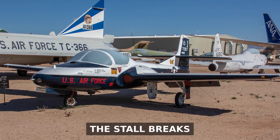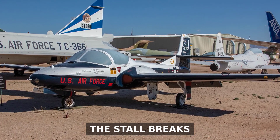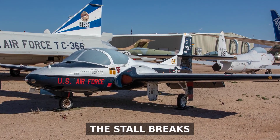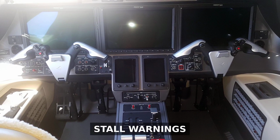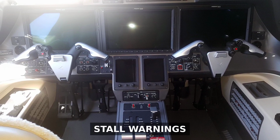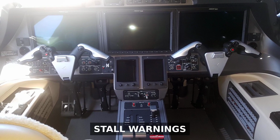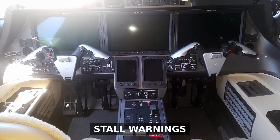In a clean stall, recovery is straightforward. Reduce the angle of attack, add power, and let the wing fly again. The problem is recognizing it fast enough. Modern aircraft warn you before the stall. A stall horn sounds at 5 to 10 knots above stall speed. In larger aircraft, a stick shaker vibrates the control column. You may also feel aerodynamic buffet, a shaking in the airframe as the airflow begins to separate.